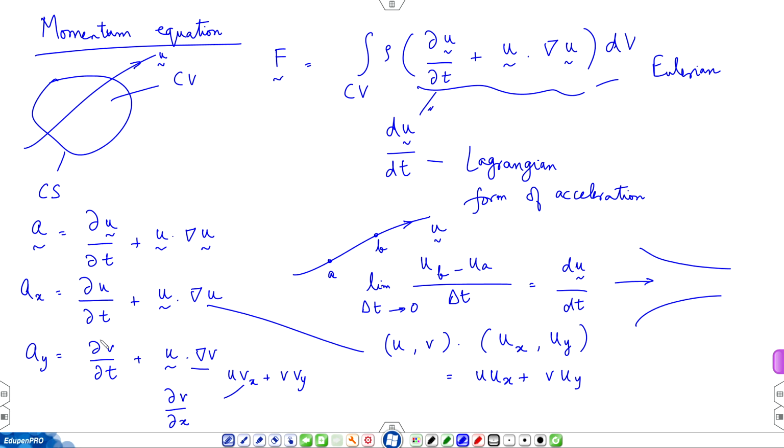So, there are examples where flow can change with time, there are examples where flow does not change with time. Similarly, flow field can have a spatial acceleration component or may not have a spatial acceleration. So, the temporal and spatial acceleration terms are independently prescribed. Temporal acceleration, spatial acceleration. The sum of the two will give you the Eulerian form of fluid acceleration.